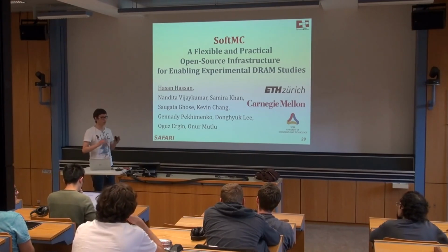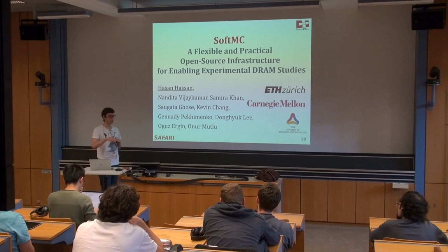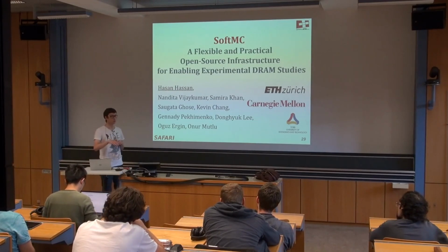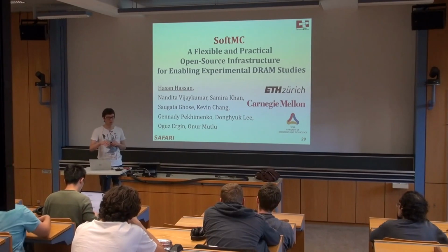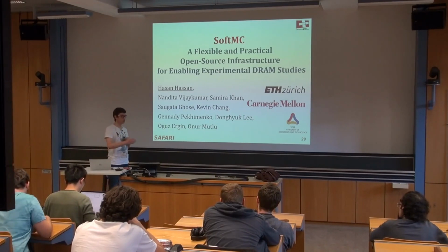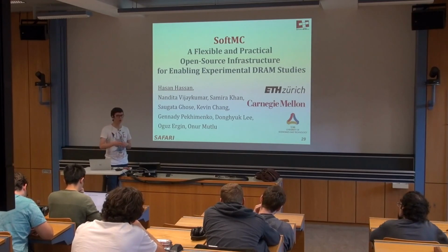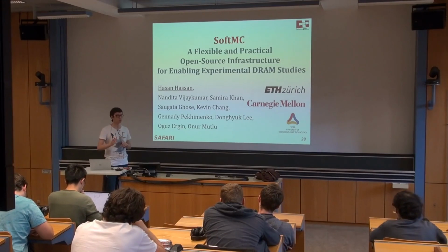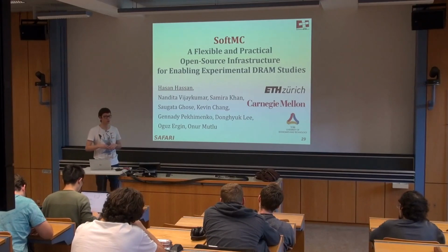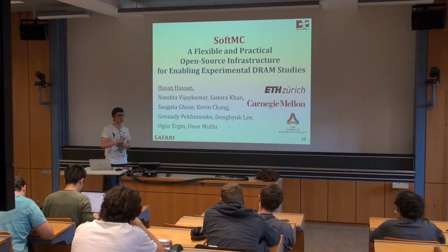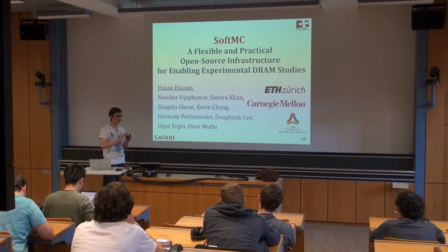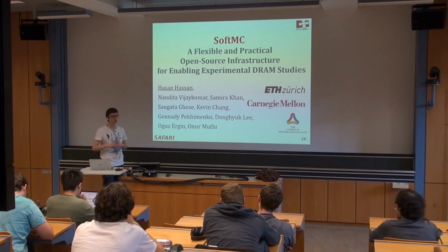We only use that DDR5 logic block, which is a hard IP block on the FPGA, right? And we kind of have to use that because otherwise you cannot communicate with the DRAM interface at very high speed. It's not like a regular I/O that you can do at very low speed, right? The interface has specific electrical specifications, and you need to meet them, and it's not easy to do with configurable FPGA logic. This is why FPGA manufacturers put those hard IP blocks, and what we are using is basically that. Other than the PHY, we don't use anything else.